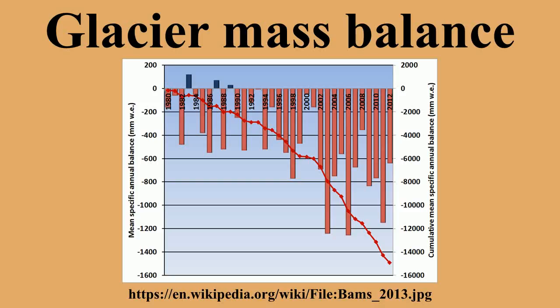To determine mass balance in the accumulation zone, snowpack depth is measured using probing, snowpit or crevasse stratigraphy. Crevasse stratigraphy makes use of annual layers revealed on the wall of a crevasse, akin to tree rings. These layers are due to summer dust deposition and other seasonal effects. The advantage of crevasse stratigraphy is that it provides a two-dimensional measurement of the snowpack layer, not a point measurement. It is also usable in depths where probing and snow pits are not feasible.